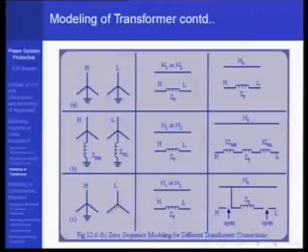Even if one winding is, like if you have a star grounded and star ungrounded system, then no zero sequence current can flow here, because IA plus IB plus IC is equal to the current in the neutral, which is 0, so I0 has to be 0. Then by the transformer action, no current can flow in the primary windings also. So therefore it gets open from both the ends. Even though this provided a path for it to flow, none can flow.